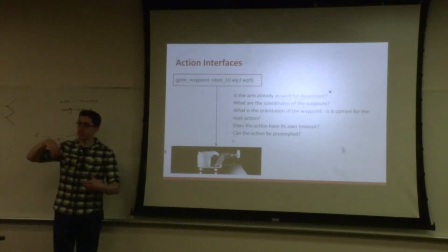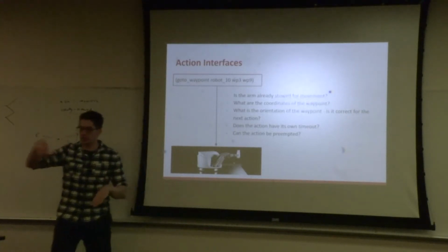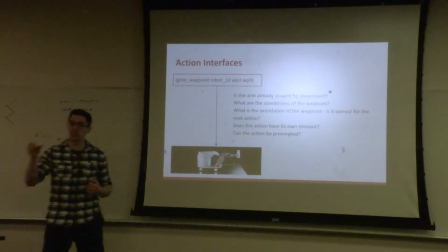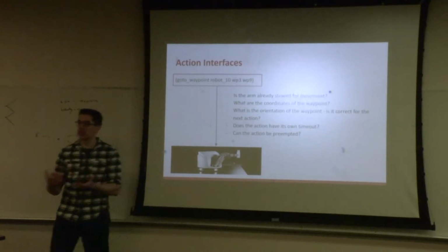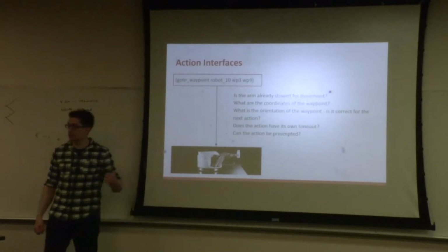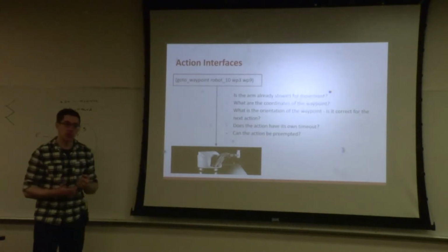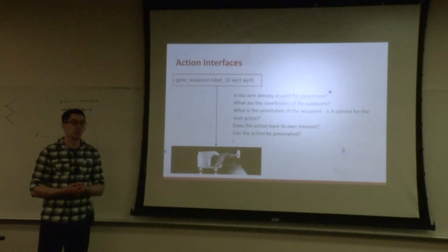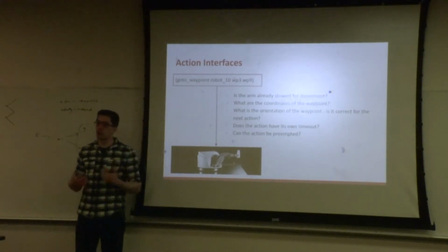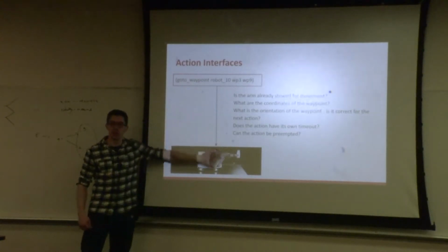But if the next action is to put the can on a shelf and the hand is blocking it, then the only way to grasp the can and achieve the next action is to grasp it from the side and move it into the shelf. The grasp planner doesn't know that. It shouldn't have to know that the next action is to put it in the shelf. But maybe it should know that there are some constraints on the way the can has to be grasped. If those constraints are going to be passed to the grasp planner, they either need to be in the PDDL model or they need to be here in this interface between the PDDL action and the lower level control.